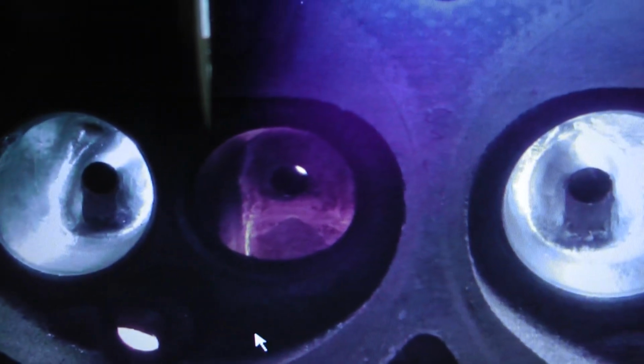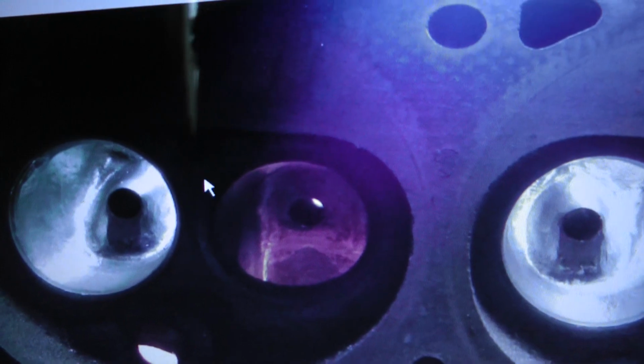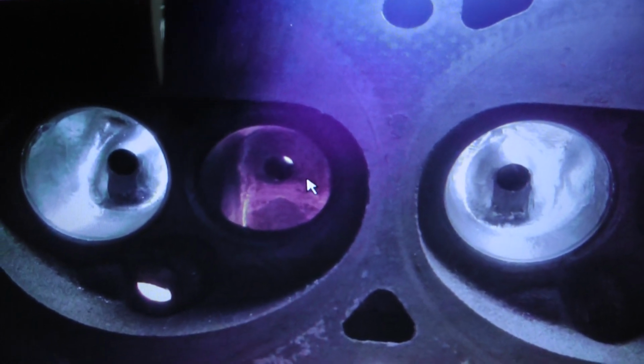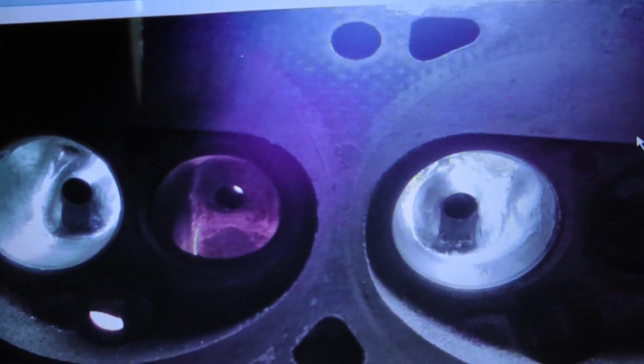Not a great shot of the exhaust. I don't know if that one was fully done yet. Looks pretty gruesome there, and these look nice and pretty. I think I'm shining a light through them. But you can see the difference. This is blended here around the bowl because there is a hump here and there's not really water jacket. And then I take my inside spring caliper to go about 550 thousandths. You don't want to go nuts and lose velocity. Because not only do you lose your velocity, you're taking more time to do it, right? So you have to have a sweet spot for that.